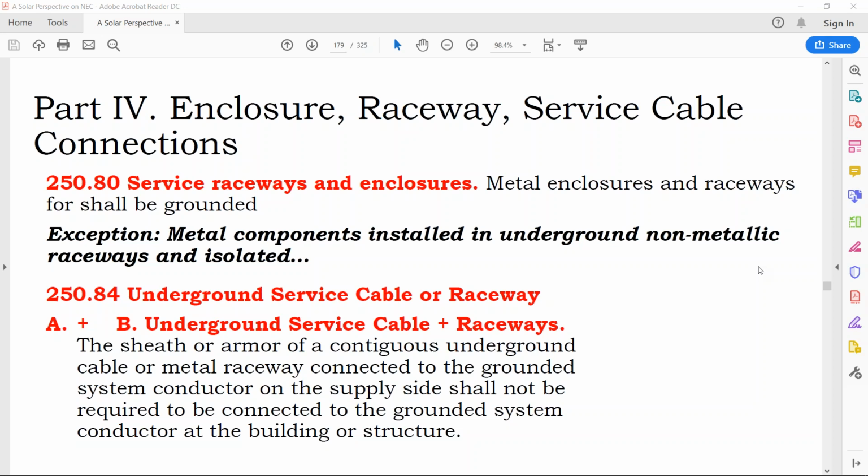But when you're just looking to support your cables as you're running across a commercial roof, you're not always having a metal box to land on. So by requiring it to be in metal conduit, then you're also requiring the purchase of metal boxes, which look ugly and clunky and are not waterproof or prone to leaks. There's a lot of water on flat rooftops. And so I think that kind of begs for plastic raceways up on rooftops.